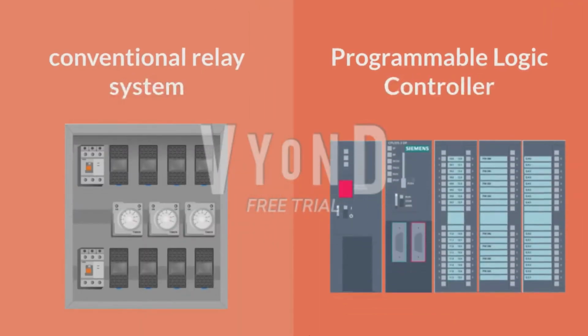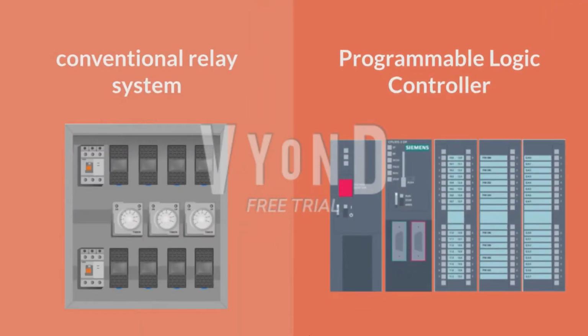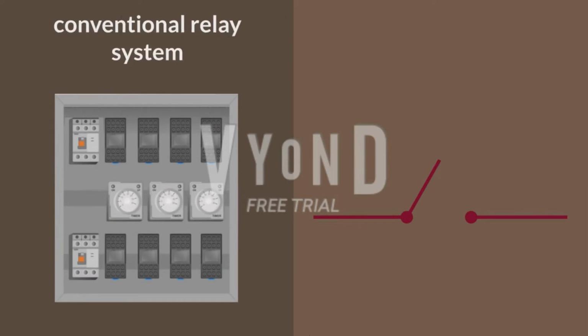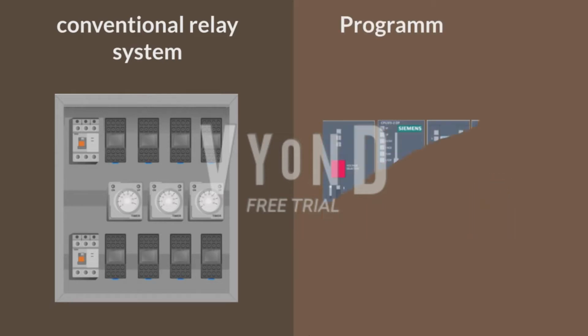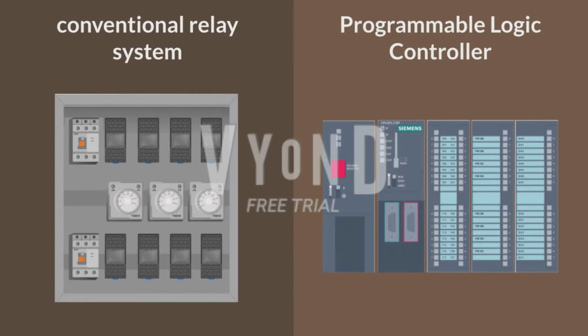The relay function is not mechanical like conventional relay systems and components, and the internal relay systems of a PLC are solid state. Conventional mechanical relays actually wear out much quicker. When a mechanical relay opens and closes, arcing will occur and eventually destroy the contact, but this does not happen in solid state type relays.